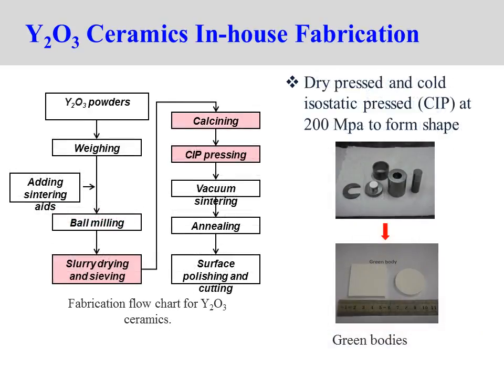Then we press all the powders. Generally, we use dry press and CIP method. After the pressing process, we get green bodies of ceramic.